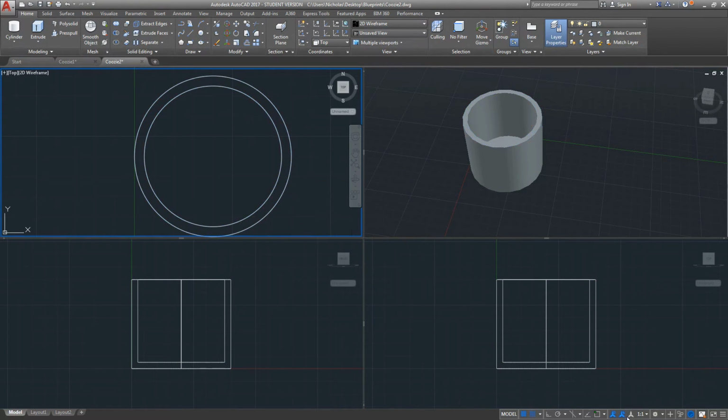We want center again, right? Bloop. See how it's highlighting in the top right box? It's highlighting the very bottom, right? So I did a cylinder because we're going to put a little hole in the bottom for drainage because, you know, bears sweat when they're cold. Center point of cylinder, boom, top of that. I think a 0.25 is a pretty good size circle for the drainage.